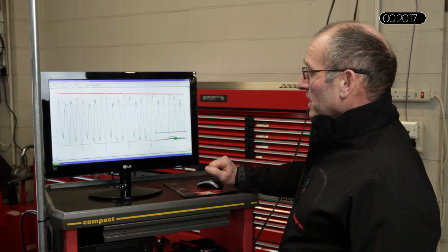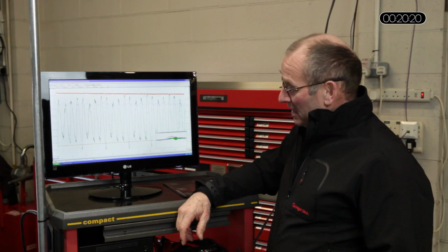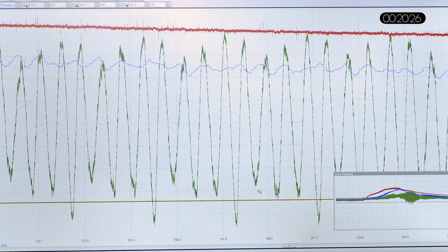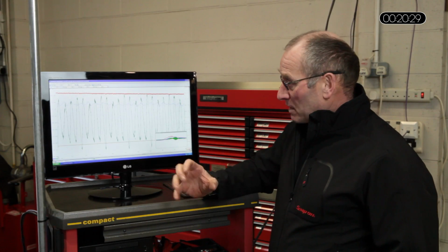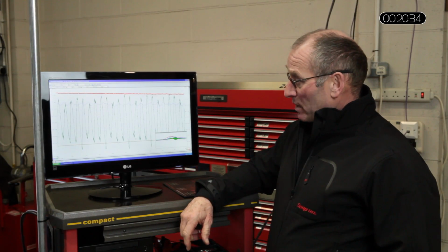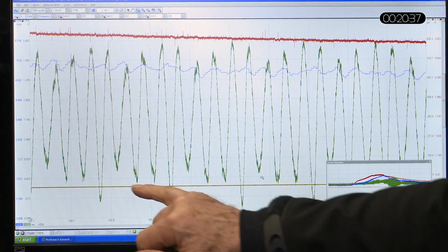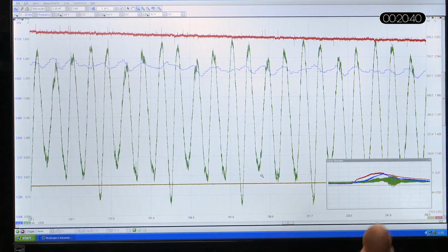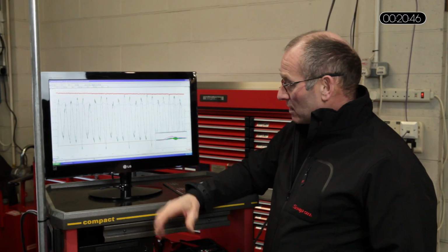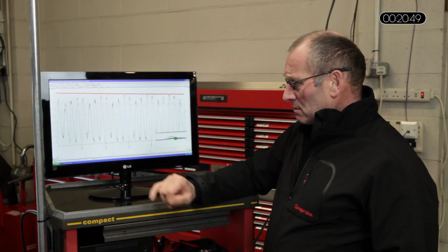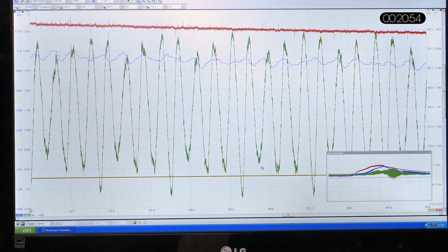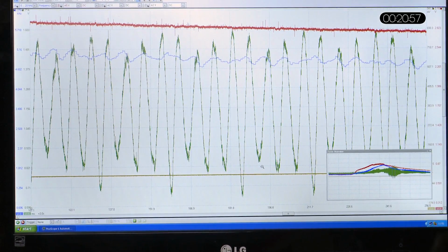And this is where it gets really interesting. You can see there is a definite pattern here. You're looking at the individual turbulence within the exhaust, in other words, exhaust stroke turbulence, and also the pressure voltage measured from this sensor. And we're getting a range from about 1.6 volts down to about 0.6. Once again, this magical 1.6 volts is a very accurate figure, the maximum figure to be achieved. But you can see that the detail in this image quite clearly demonstrates the different phases of the exhaust turbulence cycle through the sensor. So some very interesting data to be had by looking at DPF.